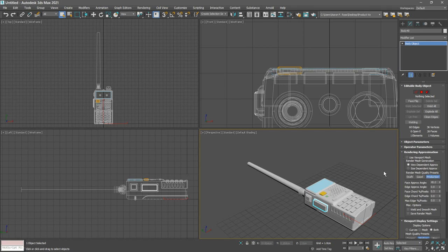But in some cases, you might want to go in here and tweak the rendering settings so that the tessellation at render time will be cleaner and you won't get jagged edges on any of your models. But as I said, for this model, the default settings are going to work fine. All right, with our CAD model imported, we're ready to progress to scene layout. In the next movie, we'll look at organizing the scene objects.